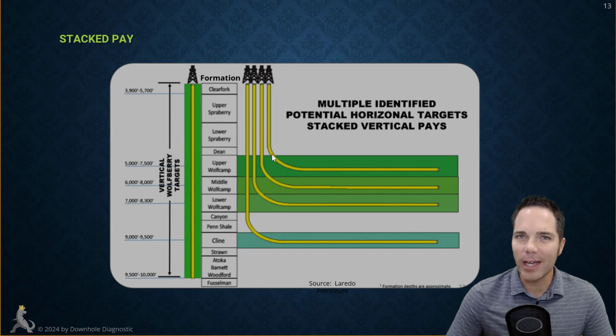Maybe you set it a little bit down into the curve, and if you're brave or you really want to take the bottom hole pressure down lower, you might set it down at 60 degrees. But of course, you're going to have increased wear and failures as a result of that. So most people are setting it up here, and you're probably going to have your TAC right around your pump intake. And so it's usually not very difficult to get a good fluid level shot on it because we don't have all this other stuff sending reflections back.